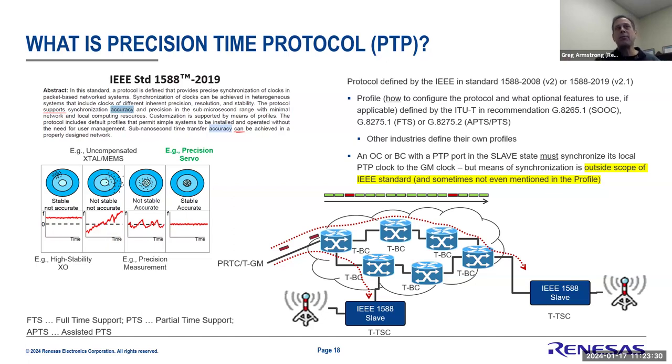So the Precision Time Protocol was just a means to identify a way to implement a two-way protocol, which again wasn't uncommon. NTP is a two-way time protocol. There are many different two-way time protocols. But what the 1588 standard tried to identify was saying, in order to get the accuracies of the two-way time protocol, we have to maybe look at getting assistance from the hardware that is sending the timing.